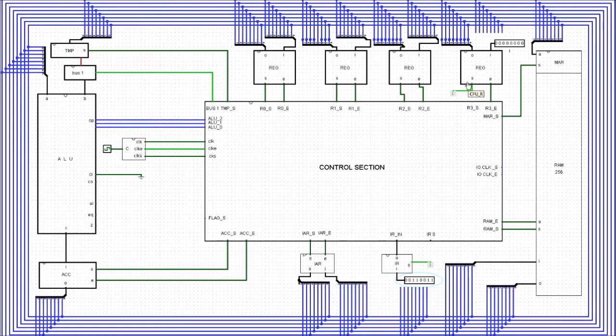So we can put a value in for the next address here. If we wanted to, we could just put any value in. Okay, we'll put all 1s. It means that the next address the instruction address register is going to go to in the execution cycle is going to be address number 256, which is the very last address on the RAM. So let's go ahead and we'll see how this is done inside the control section.